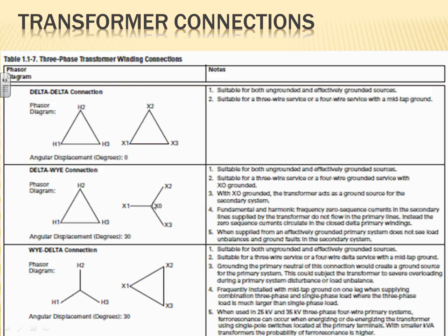The nice thing about the delta Y grounded here is it will trap all the harmonics. That's why we like them. When they have harmonics, like when we feed our receptacles in here, they will trap the harmonics inside the transformer and do not reflect them back into your power system. So it traps them inside. The advantage is they don't pollute your other power system with harmonics. Disadvantage is your transformers will have circulating current because of harmonics in the Y, in the delta here,